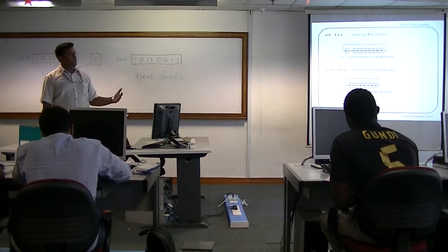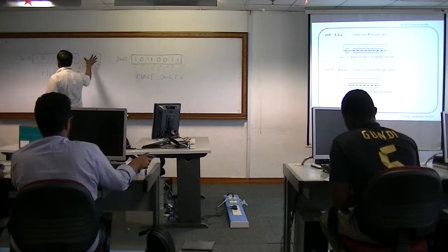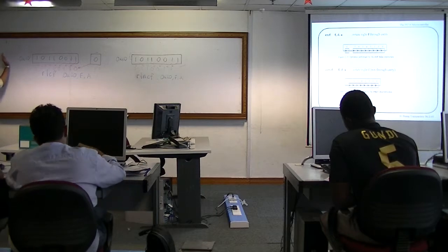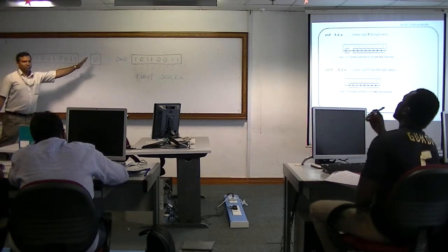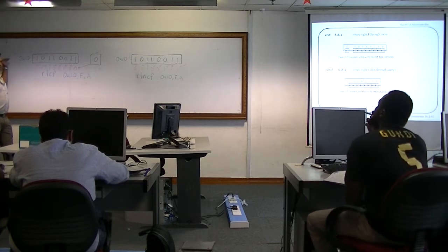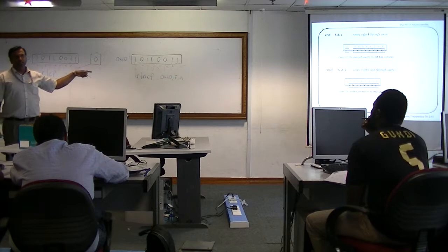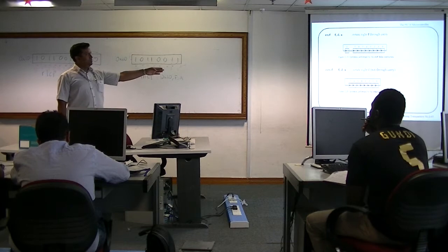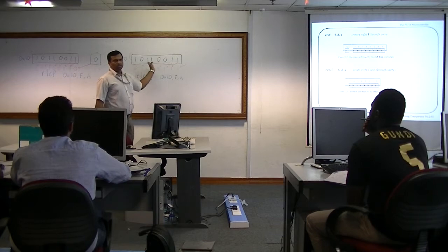The next thing is rotate right. The same principle. The only thing is now the carry bit is positioned on this side, because when you rotate left, you start to push from the most significant bit. You all understand? Because for rotate left, you need to push everything from here to here, to the left. Rotate right means you push from left to right. So that's why the carry bit is positioned on the other side. Likewise, the same principle, it will all shift by 1. And the same thing with rotate right, not through carry. Everything will be shifted towards the right.